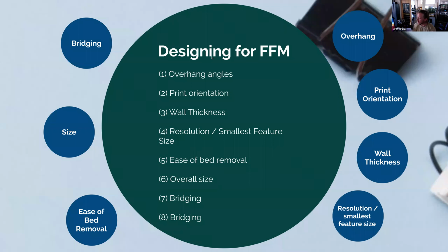How quickly does the filament dry or harden? That depends on the material, but pretty darn quickly. I would say many materials, nylon, ABS, PETG, they actually have to be printed in a heated environment. In a closed environment, so that you get proper adhesion between layers. Whereas PLA, for example, you want it to cool as fast as possible, and that's just a function of how the layers bond. But most materials you can take off the print bed right after it's done printing, without the risk of, say, burning your hand or something like that. Does that answer your question, Mason?